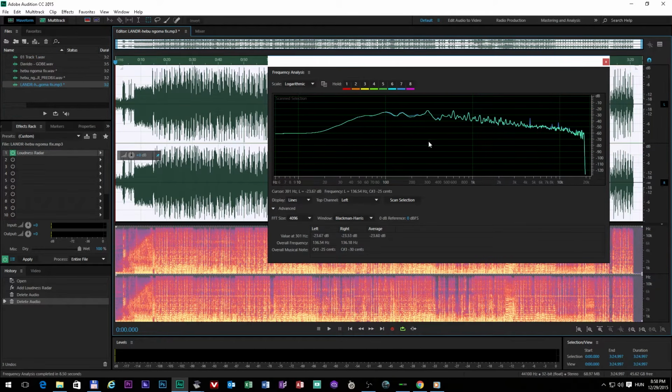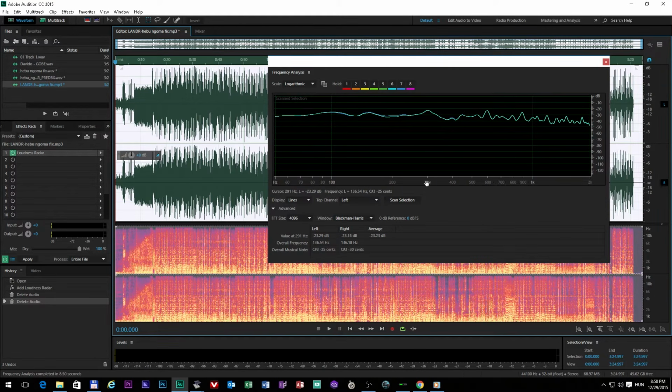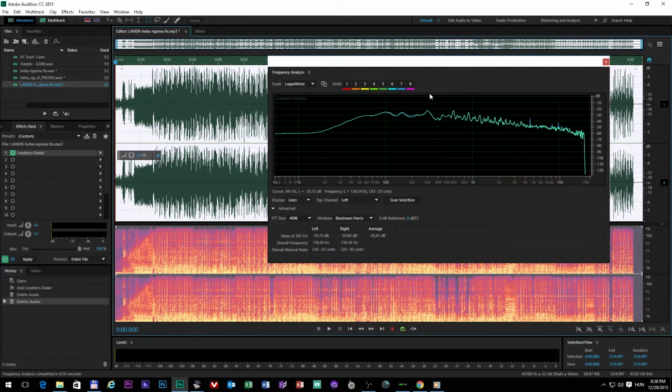Look, this bump. And actually this 300 hertz and this 200 hertz is a really problematic, annoying area if you want to play your song on some kind of PA system, because this 200 hertz is exactly the place where the PA systems start to do a cut to the next frequency band.